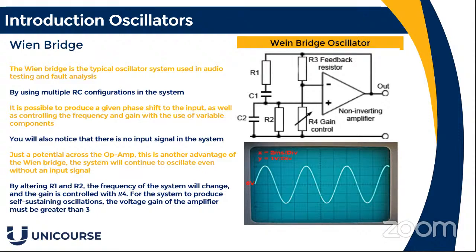And in the quite old style generators, or signal generators, that were used by engineers for testing audio equipment, TVs and radios and stuff like that, what you would have is a group of either discrete transistors, or if it was a bit later on, an op amp, and you can set different frequencies. You can have a range from about 50 hertz up to a few megahertz. So they're quite a stable circuit.